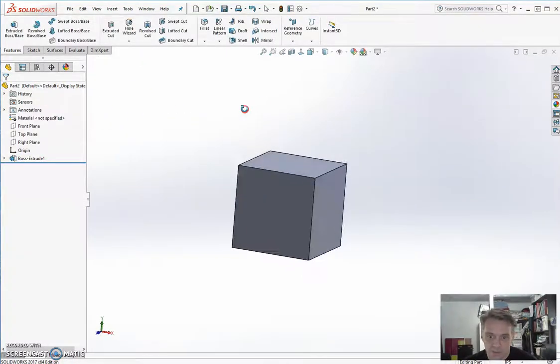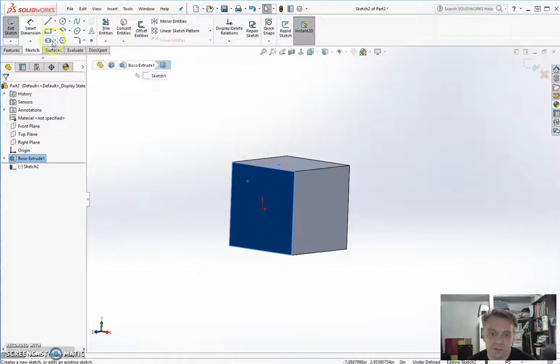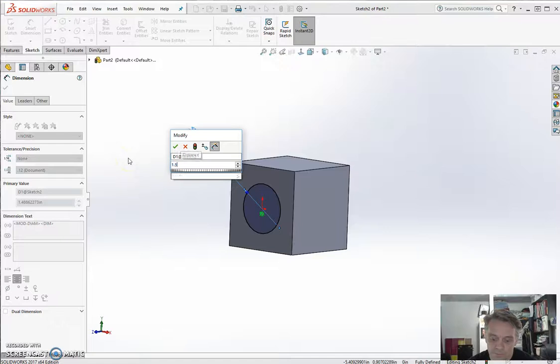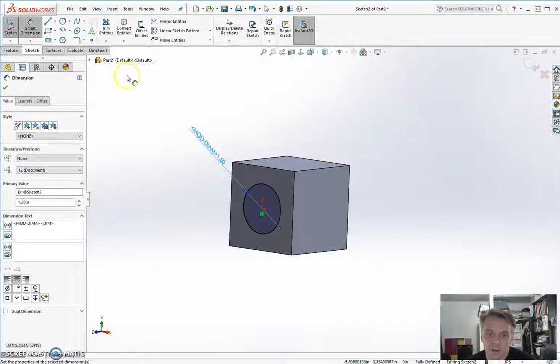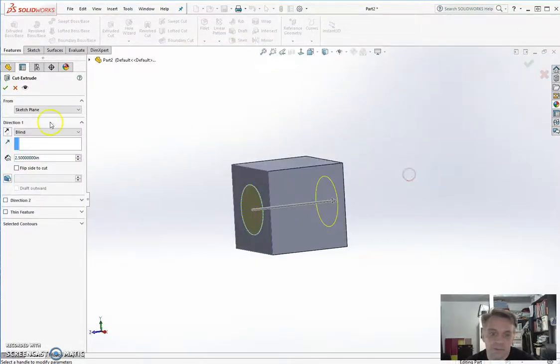Now I'm done. So the difference between the section of tools over here on the top left is that these create geometry where nothing was, and then the next set removes geometry from existing parts. So if I were to create a quick sketch on this plane, this surface, I could now extrude this hole, and as with the extruded boss tool, I could choose something other than blind.